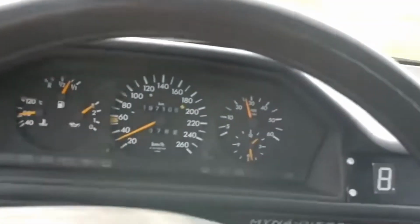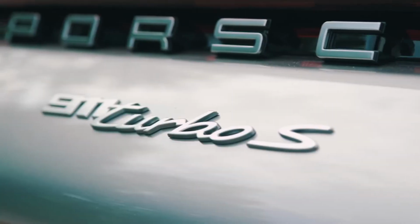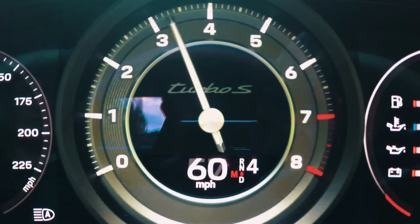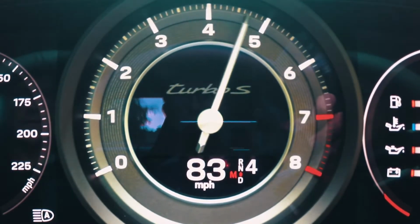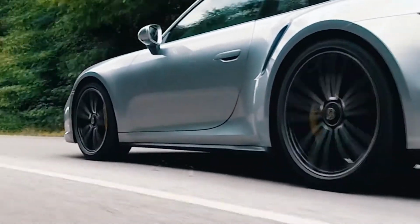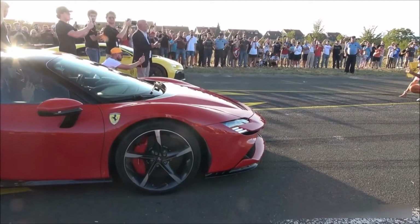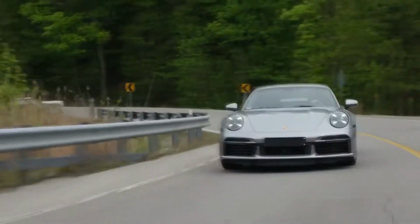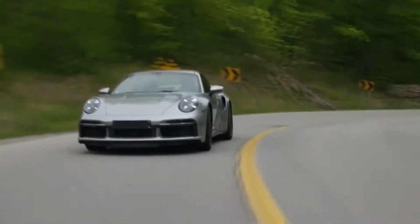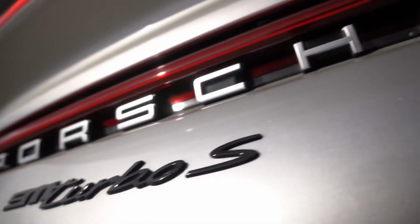In simple terms, a turbo is an air pump that enables more air to be pumped into the engine at higher pressure. Turbos usually offer up to 70 to 140 horsepower extra. Turbos are connected to the exhaust system and make use of the waste energy from the exhaust gases. The downside is that the turbos need to build boost first before it can be used, which is known as turbo lag. For example, the Porsche 911 Turbo S has a 3.8-liter twin-turbo flat-six engine, which has some turbo lag when putting your foot down on the accelerator.